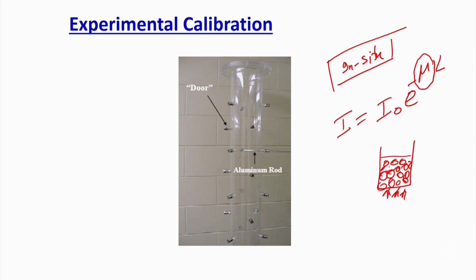In the packed bed, suppose this is my tracer particle, the red one, and these are the detectors placed. The attenuation will be more because all the solids are perfectly packed, so it sees a lot of solids. Depending on density, gas has very low attenuation, while a material with higher density has very high attenuation. So you will see different counts on all these detectors.